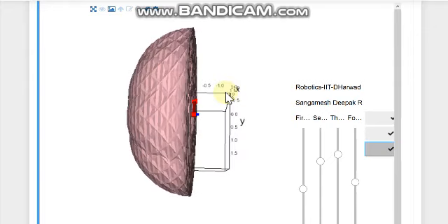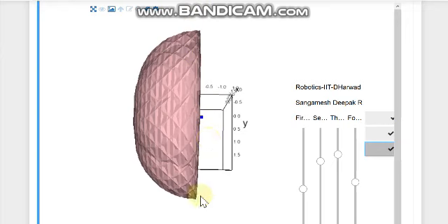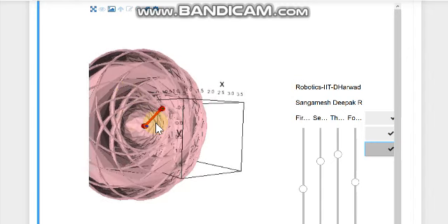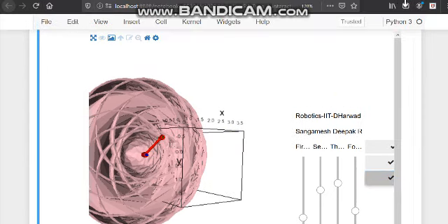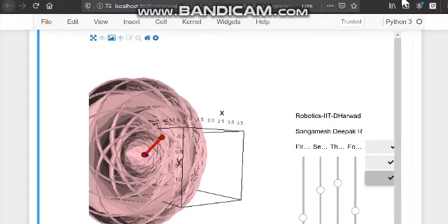Of course, there is no material beyond this particular line. But otherwise, between this surface and this surface, the entire space is filled. It means point O4 can reach any point in that space. So this is the workspace of the robot, which we were looking to find out.